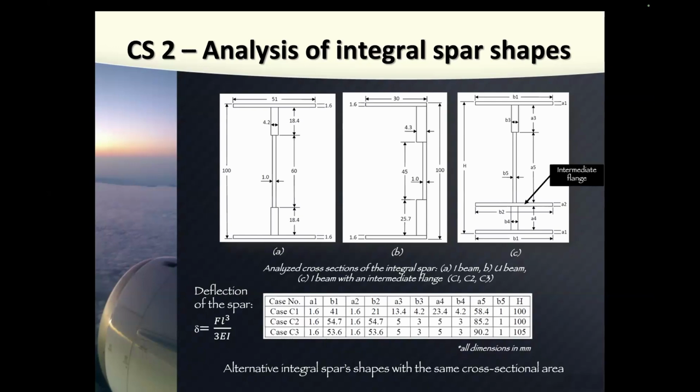And so here we played with different designs. This is again an I-beam, like the original I-beam. But what was the difference? The original spar was differential, made of 5 different parts, four caps and 1 wall. Here this is an integral design obtained by laser beam welding. So what's the difference? Mass will be even less because we don't have rivets here. We don't need rivets because we have an integral structure.